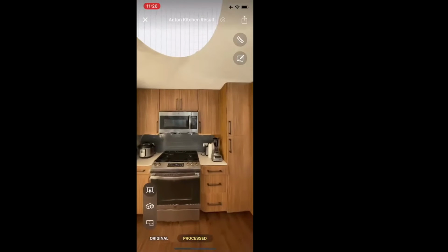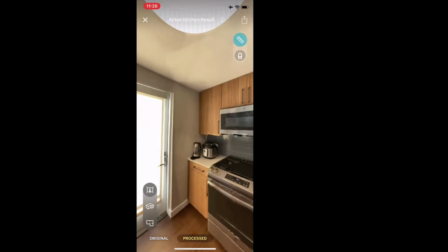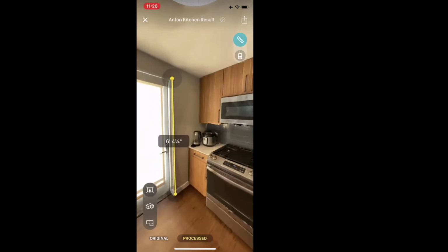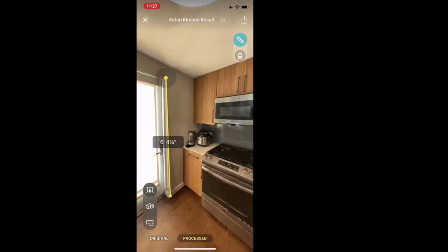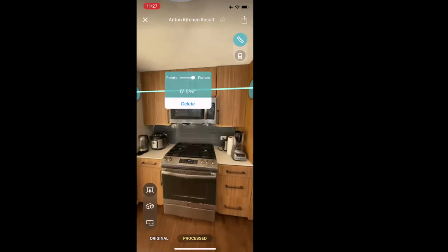So in each of these modes, you can actually take measurements. And if I click, for example, just 2 points, I get this measurement. And you can change whether you'd like to use the metric system or the imperial system in settings. And we also automatically recognize if you try to measure the distance between parallel planes. So if I click on this plane and this plane, we automatically recognize this. So you can measure a more accurate distance between the planes. Or I can switch to points and you see that the distance might change in this case.